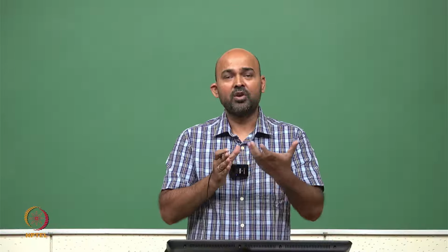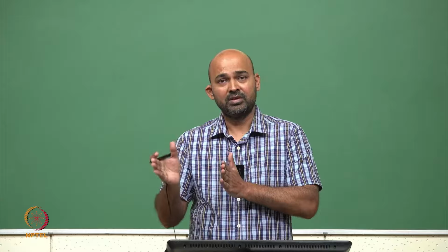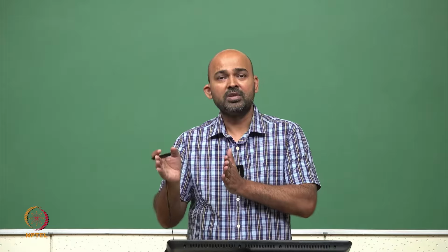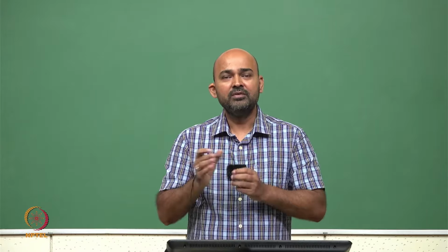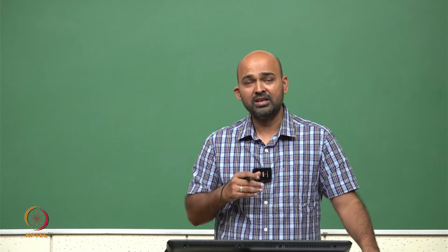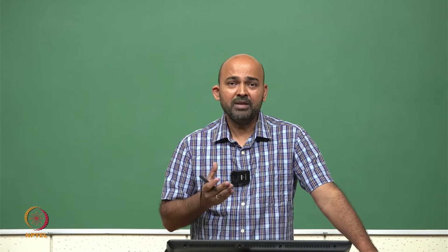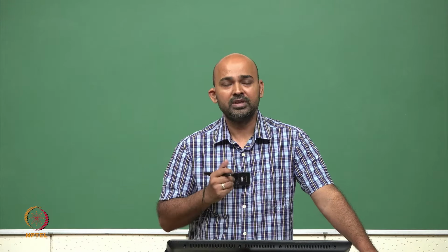So, now we have some definitions for data as well as clock. When the clock comes, at what time should data be ready, and after the clock, how much time should data be available? So, then we have some very important definitions in synchronous design or sequential logic design. These are the setup time and hold time of these circuits.